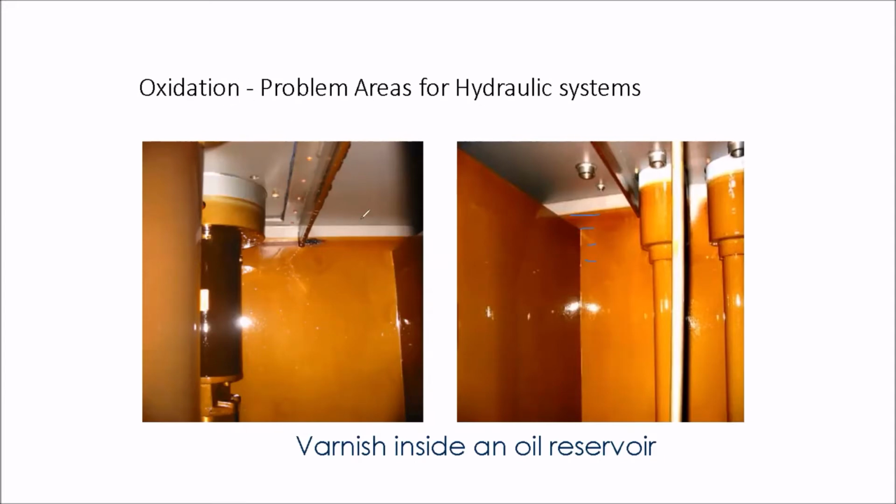Once oxidation happens, the oil will stick on the surface of the tank and become a varnish-like, sticky surface. This will collect dirt and particles, and in the worst scenario it will damage the components, or the movement of the components will be jammed. This is an oxidation problem.